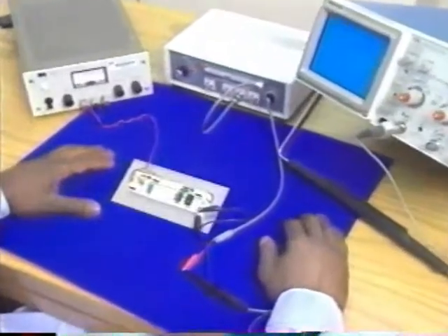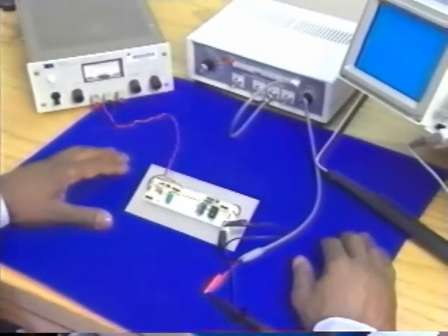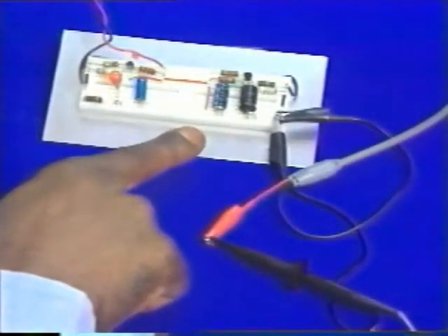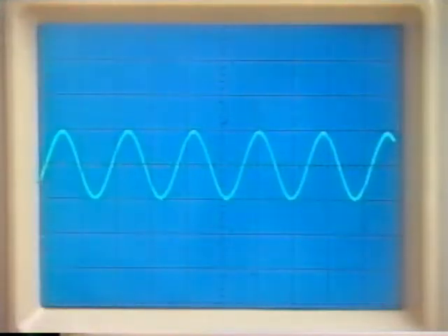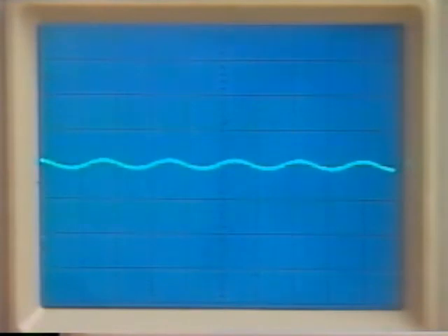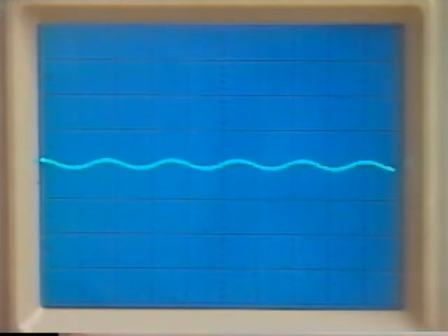Let's use an oscilloscope to examine some actual amplifier circuits and watch the effect of input resistance on the signal source. The amplifier on the right has a low input resistance. Without connecting the signal source to the amplifier, you can see on the oscilloscope screen that it has an output of 2 volts. This is because there are 2 divisions of amplitude at 1 volt per division. Connecting the signal source to the input of the amplifier and turning on the signal source causes its voltage to drop. This means that the amplifier has loaded down the signal source, resulting in a reduced input voltage to the amplifier.